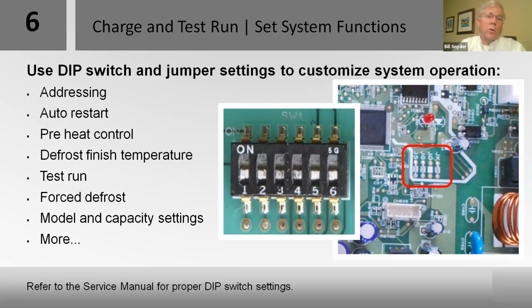If you put an external sensor on, like a thermostat on the wall, it's going to sense the temperature like an MHK2, then we would typically sense the temperature at the control and we would do a thermal fan off. Now the MHK2 on most units, we can just set the thermal fan off from the menu. But on some units, you have to go in here and actually cut a jumper.